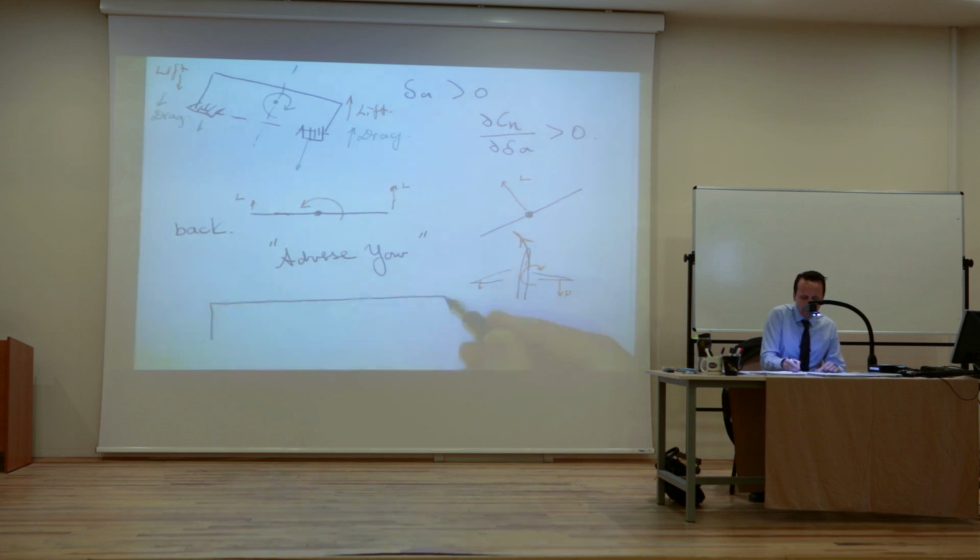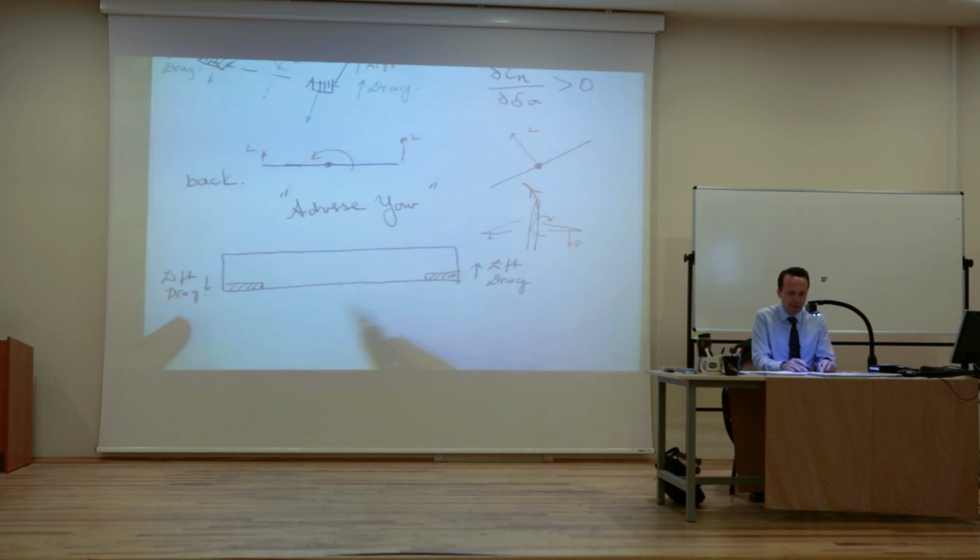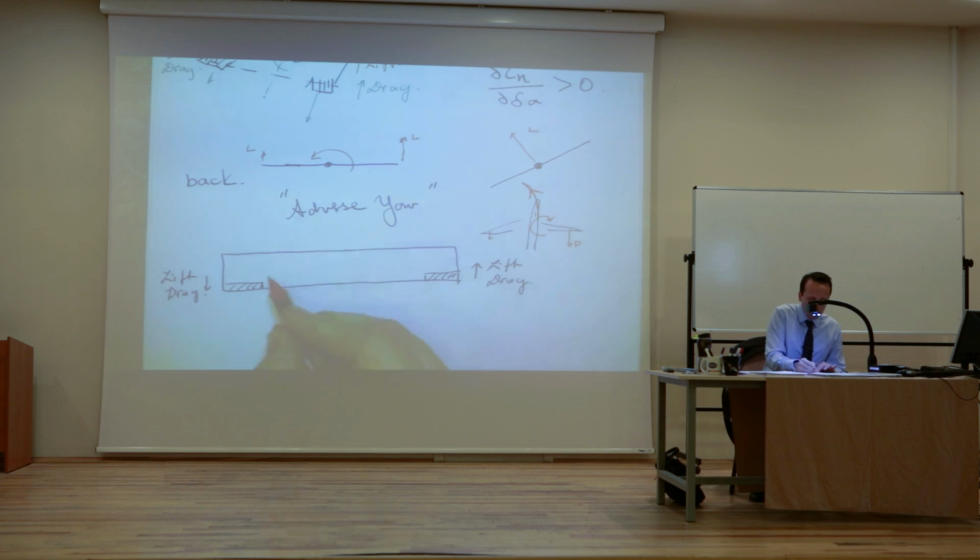One of the things you can do is, let's say your aileron is moving in one direction and the other one's moving in the other direction. Let's say you have high lift and therefore high drag, and here you have less lift and less drag. But you want that lift difference, and the drag you don't really like. What you can do is you also want to have more drag on this side. What you can do is put a spoiler over here. This is what we call a spoiler. The spoiler will also, of course, be on the other side.